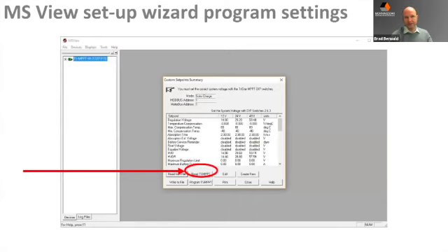With batteries also growing in intelligence and communications, there are more opportunities for connectivity with them as well, both with the site equipment and also with the charge controllers and inverters. Clearly, there's a lot of closed loop interface going on between both charge controllers and inverters in the industry. For these existing products, we provide support for, at the very least, open loop control. And we have configuration options here where you can load presets for these battery types using MSView. You can program it into that controller, and then your controller is pretty much preset for that specific battery type.